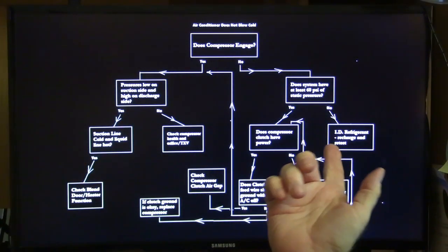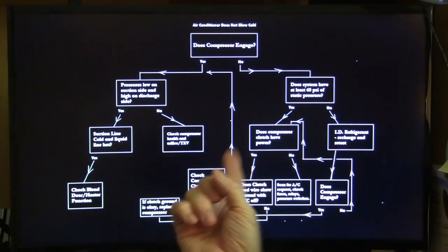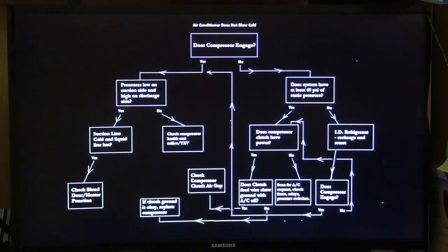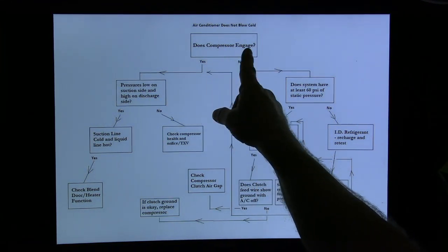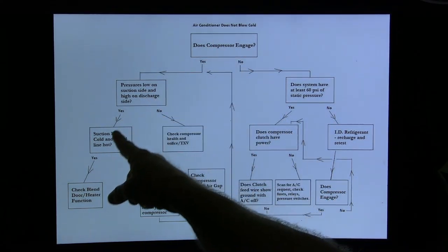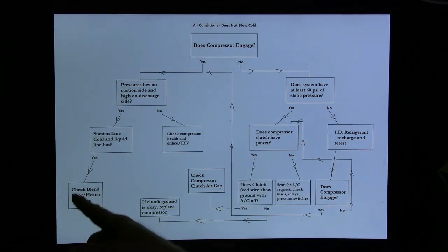Now this right here is a chart. In a minute I'm going to turn this white so you can pause this and maybe do a screen print of it. I put this together for my students and it works pretty well. Air conditioner doesn't blow cold. Does the compressor engage? If it does, you go down this way and then you follow these lines.